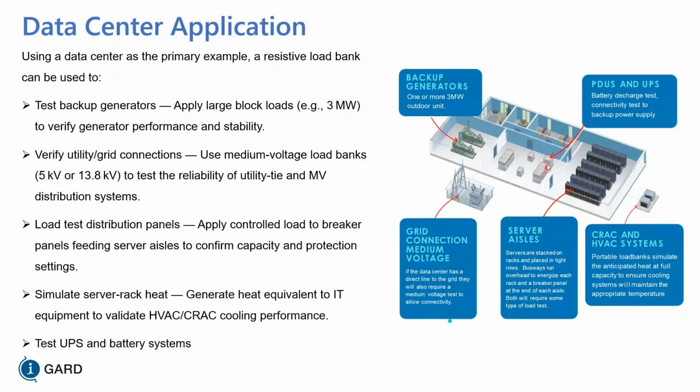Generators over here, distribution center. I don't see the battery room, but it's in here someplace. Your grid goes down, you want to make sure your generators can pick up. And the generator should pick up faster than your UPSs should tail off. So testing backup generators is crucial, because we've had power failures before where backup generation just never picked up.